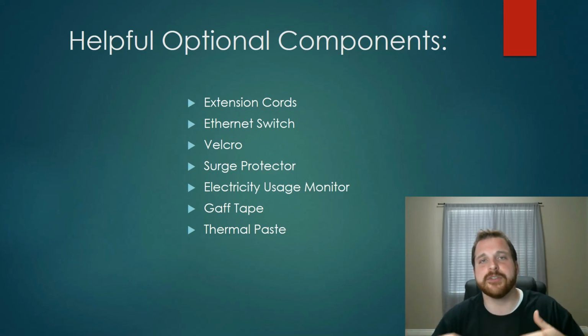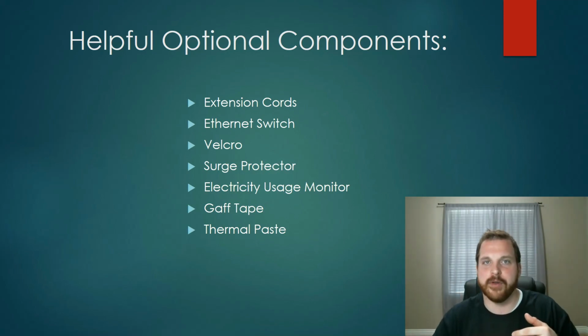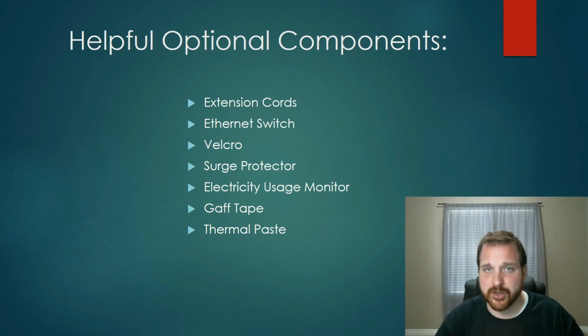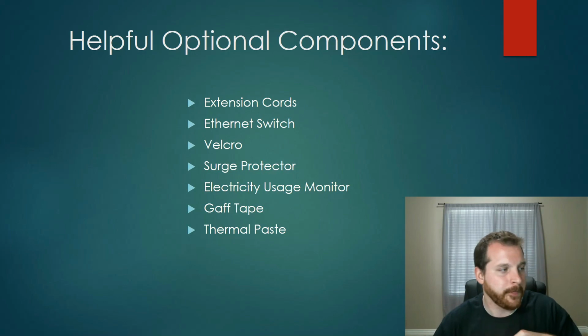If you're going to be using this rig as also a VR rig, a virtual reality rig, or you're going to be gaming on this rig as well, you will want to use a higher-level thermal paste than the one that's on there. It's been on there for a while, it's been stocked on the shelves, and it's generally really cheap thermal paste. So I'd recommend getting some of your own. You wipe off the stuff that's on the old one, you apply your new good thermal paste so that it really does help with the heat distribution on that CPU.